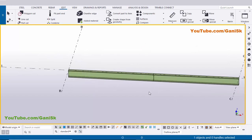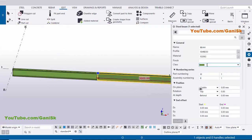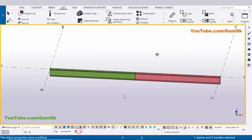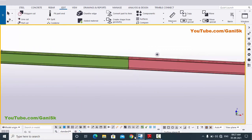Use the shortcut Control 4 for render view. Now I'm going to change this beam color, so double click on it. Now let's take class 2. Now click on modify and close it. You can see now I have two beams. Okay, now I'm going to create a connection between these two beams with this example.